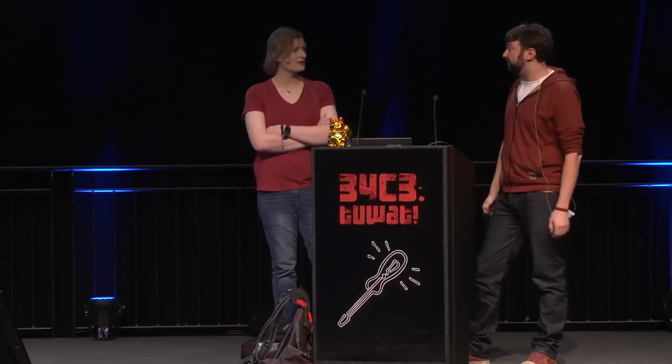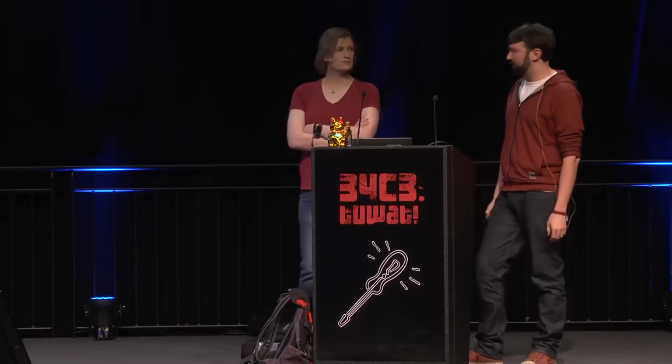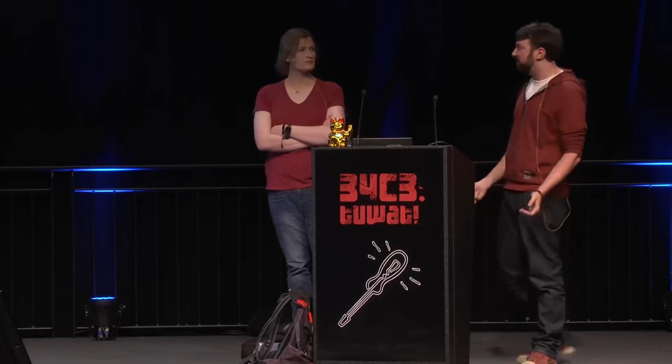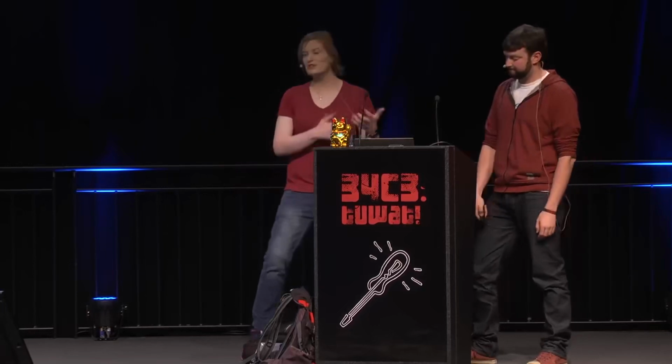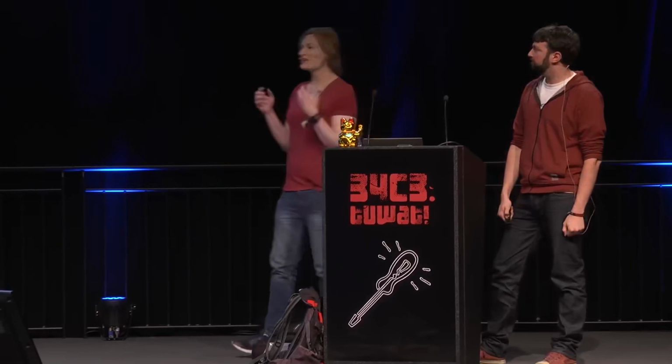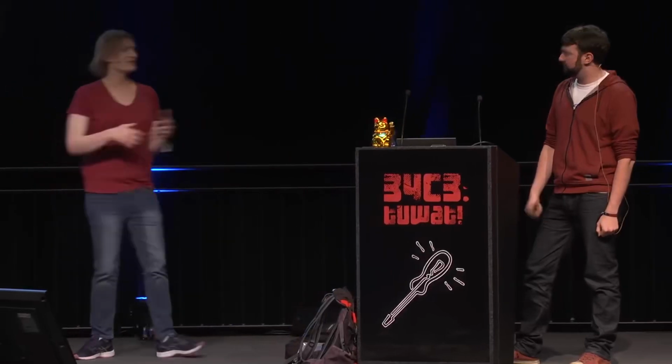And there's a fair chance that the descriptor stuff might be really solidly written. It might even be implemented in hardware on the peripheral. But those USB vendor requests that someone's thrown together the day before they have to ship this piece of hardware, they might be written in that slightly more sketchy style of let's just decrement an integer and see what happens. Or there might be more than one thing going on in the hardware as a descriptor is sent out, and that makes it very difficult to glitch, because if you start glitching the descriptor request, you might also knock out something that is responsible for the core functionality of the device, and the device's memory bus may go down, right? Yeah. So being able to explore a lot of that is really important.